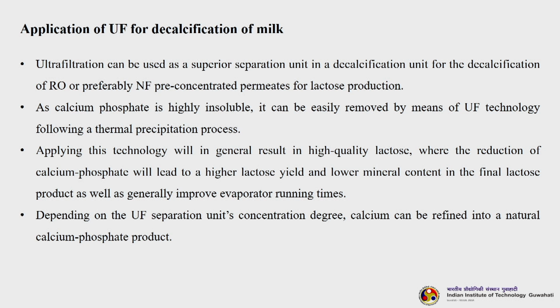As calcium phosphate is highly insoluble, it can be easily removed by means of ultrafiltration following a thermal precipitation process. So, applying this technology will in general result in high quality lactose, where the reduction of calcium phosphate will lead to a higher lactose yield and lower mineral content in the final lactose product, as well as generally improve evaporator running times.